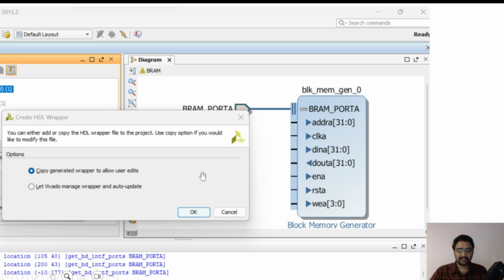I will show you the VHDL script. You will understand. But imagine taking an IP block and declaring the pins for it, checking the pins, and all these pins were not assigned in the same VHDL file for a block. So now this block VHDL file has a draft, and for the draft, if we click on generate HDL wrapper, it has all the input pins and output ports defined automatically.